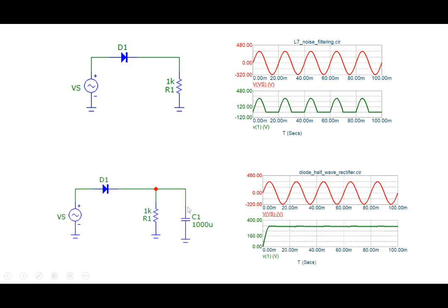And then all I did was put a capacitor across it here, a capacitor of a certain magnitude, and look at the waveform now, right? The output here has become constant, right? So we have gotten a constant voltage. We applied a sinusoidal here, and we've gotten out a constant voltage, which is what we desire. So again, the principle is the same.